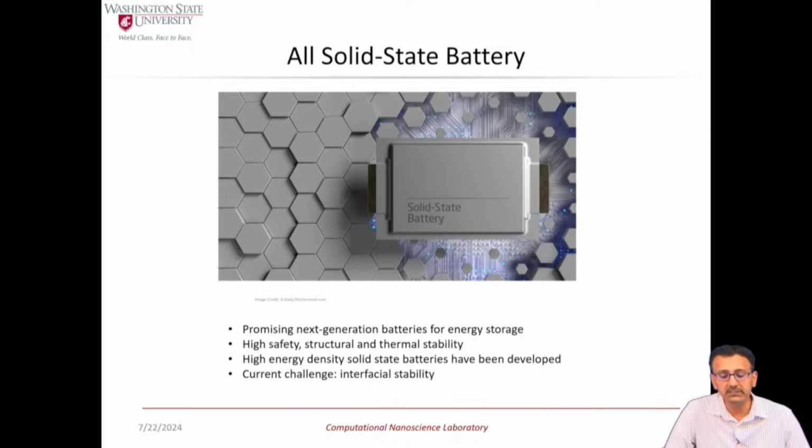It's very promising as a next generation storage because primarily they are very thin, so you can use an electrolyte which is a thin film, so they are relatively small in dimensions, and they are very safe because you don't have electrolytes that are volatile. So, that achieves quite a bit of high safety here. And the energy density of these solid state batteries has also improved quite a bit. They are not yet comparable to the standard lithium ion, but it's getting there.